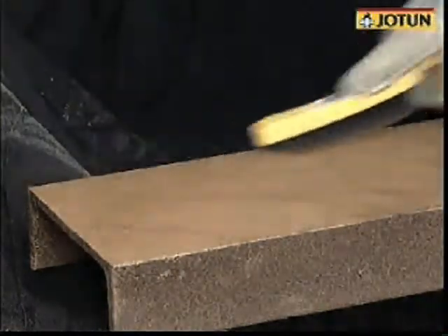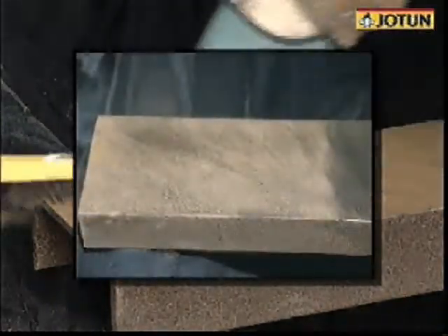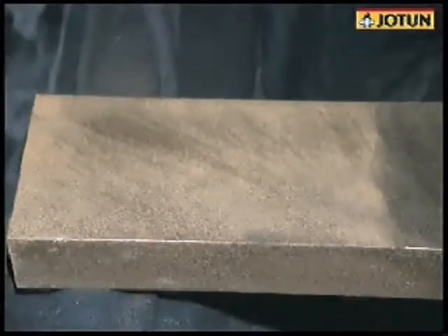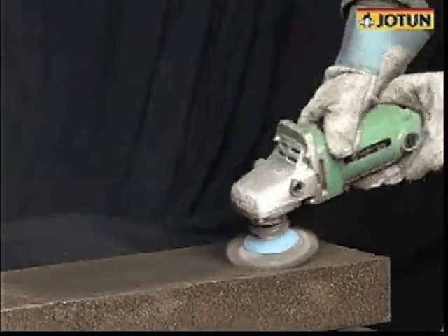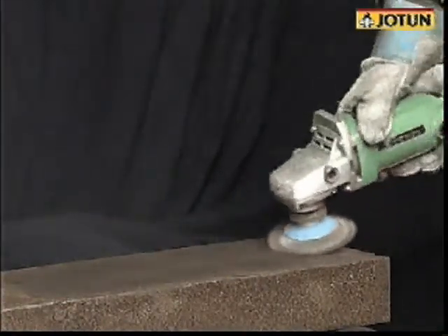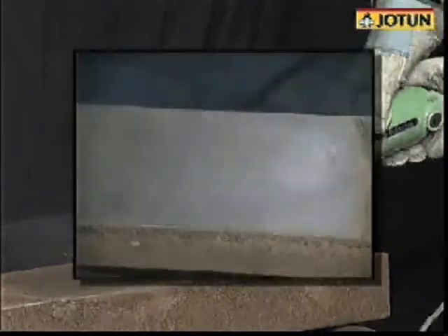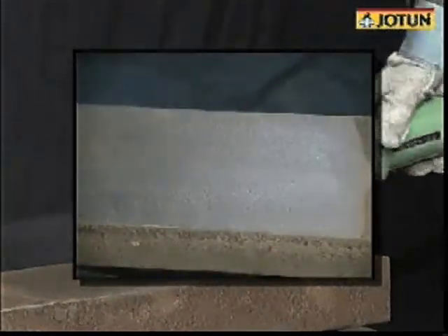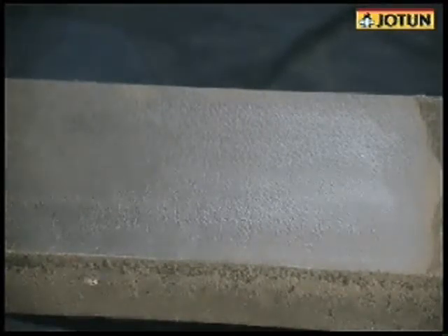Wire brushing is one of several alternatives to blast cleaning, where blasting is not permitted or not feasible. Under ISO 8501, thorough wire brushing is designated as ST2, while ST3 indicates very thorough wire brushing. To speed up the production rate, rotating wire brushes can be used. If care is not taken, there is, however, a great risk of polishing the surface, which will give a poor anchor pattern for the paint system and reduce the performance.